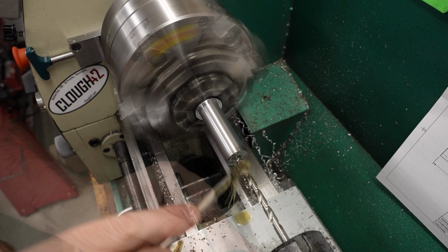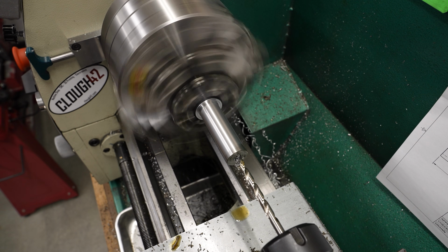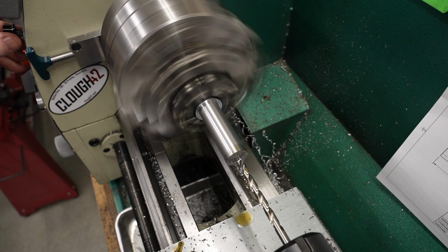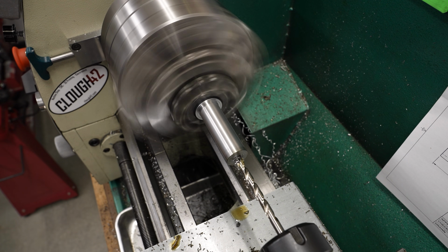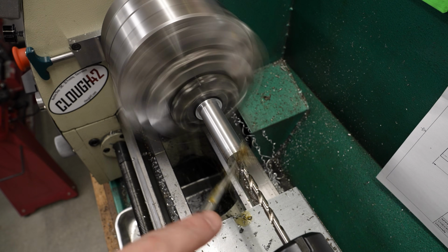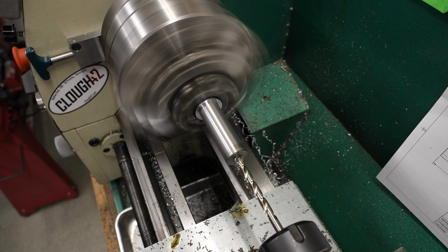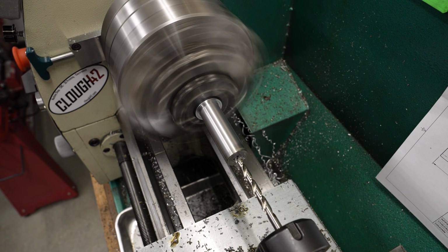And I want to make sure that I have a good deep hole to get this drill started in the right direction, make sure it can't wander. We'll give this a little lubricant, a little speed, and we'll just push this through. Now, this is a relatively small drill for the depth of hole I need to make here, so I'll be pulling it out and brushing off the chips periodically.